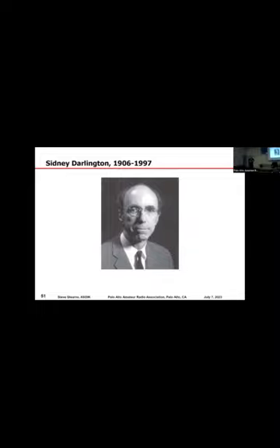There's another variation on that connection called the Sziklai pair. The Darlington pair and the Sziklai pair are the two interesting ways to connect two transistors to act like one transistor. One uses an NPN and a PNP, and the other uses two PNPs or two NPNs. So that's the difference. In one connection, the Darlington, both transistors are of the same type, and in the Sziklai, the two transistors are of opposite types.